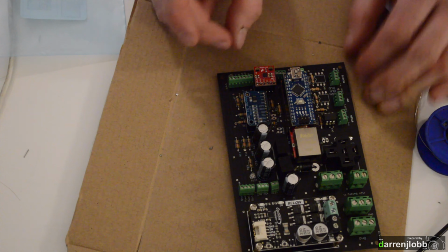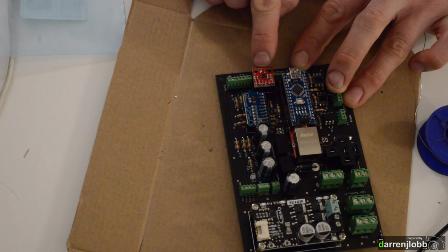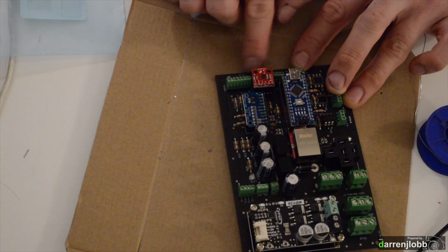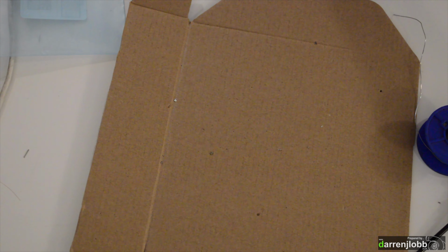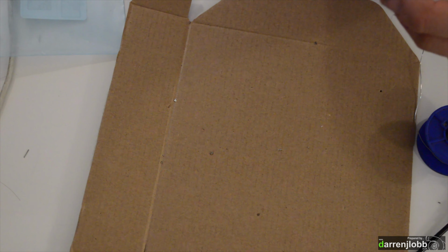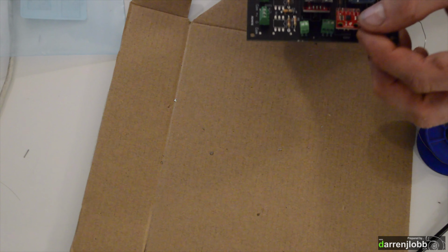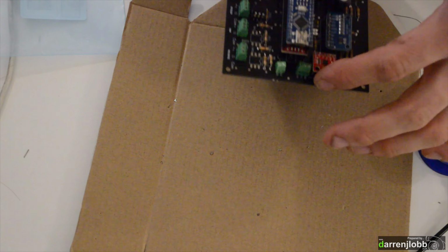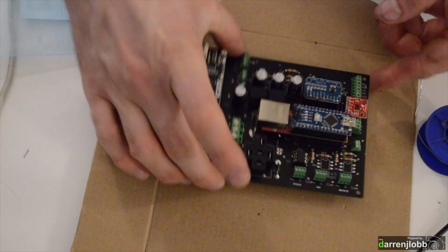I've read a few people who think they've been having a little bit of trouble with vibrations. You can see there's a little bit of play in that board. There aren't actually holes drilled in the board, because otherwise we could mount that on there. So I don't know if we've got any traces in the way where we could possibly drill some holes. Or failing that, we can use the same system and just a spot of hot glue gun to stabilise that board so it can't vibrate, because I think some people have been having a little bit of trouble with that. Okay, so that's the PCB pretty much together.